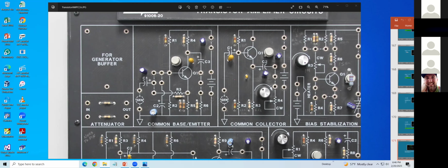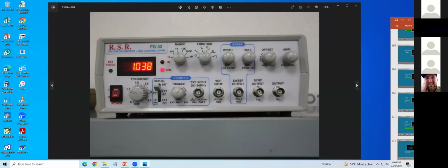Exactly, very good. The knob here, you pull it out. Normally they don't pull it out, and going down to minimum they get around 1 volt. They cannot go to 300 millivolt. So if you want a small voltage, pull the knob out.